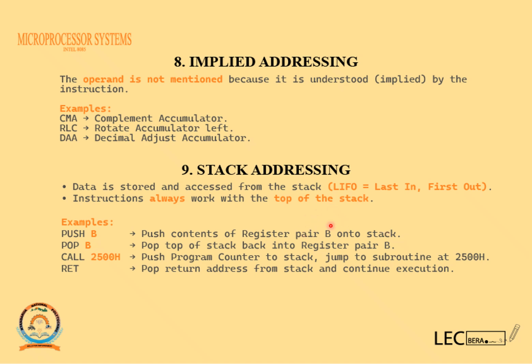When you want to store data, so that if something happens to our microprocessor we can retrieve the last data we were working on, this instruction helps. If you are working on the data held by register pair B, C, and we push those contents to the stack memory, we can retrieve it and know where we stopped during our last instruction.